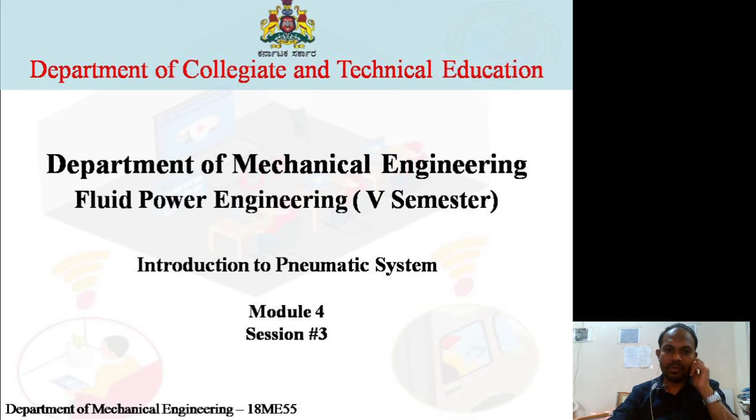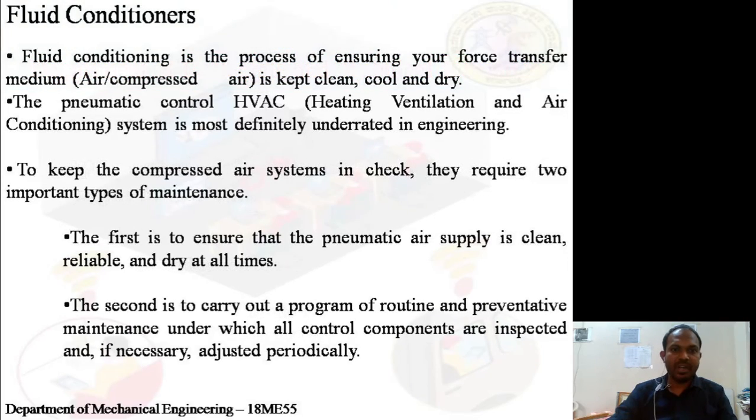So majorly, what do you mean by fluid conditioning? Conditioning is needed because, as we know, normal atmospheric air will have dust particles, chemicals and moisture content, and it will also have some temperature. So it has to be cleaned before it is sent into the pneumatic system. Second, even the compressed air will have a higher temperature. If it has to be used in the pneumatic system, it has to be cooled, cleaned, and free from moisture content.